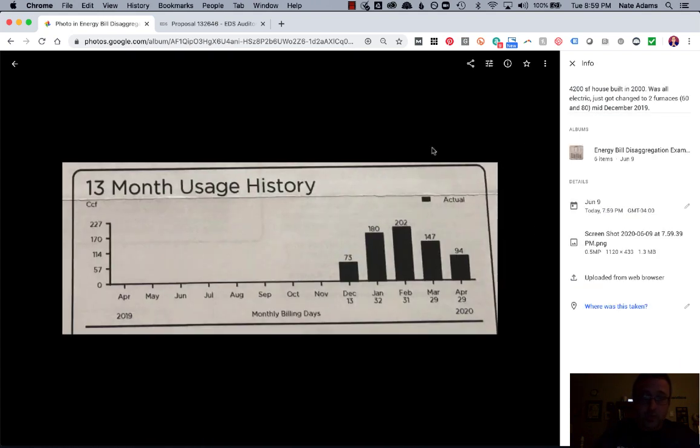for HVAC. Now this house, it was also kind of nice that they had some pretty clean gas bills. So this furnace system went in mid-December, and then January, February are our two coldest months. And this is pretty low usage for a house this size. So overall, it's 700 therms between these 4.5 months. So I'm betting that this house is going to use something like 1,000 therms a year, 1,100 therms a year.